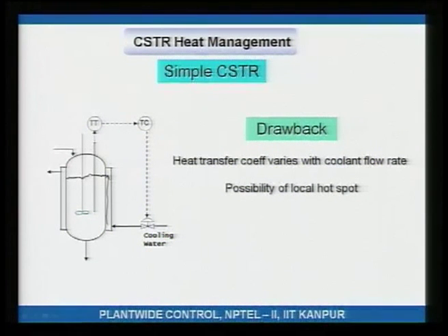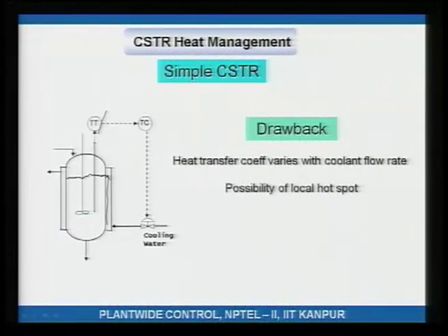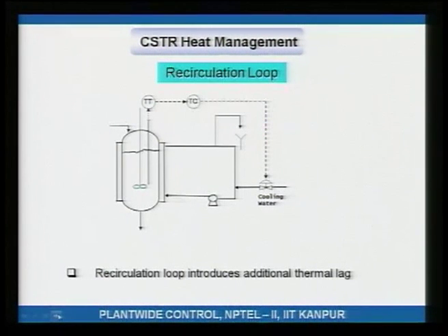The inlet of the jacket is cold, the exit of the jacket is hot, all right, because the coolant flow is low. Okay. So, even though this is what you would think conceptually should be done, this is never done in industrial practice. This is never done. Please note this down. Okay. What you will find is, actually this is also not done, but the recirculation loop is what is done.